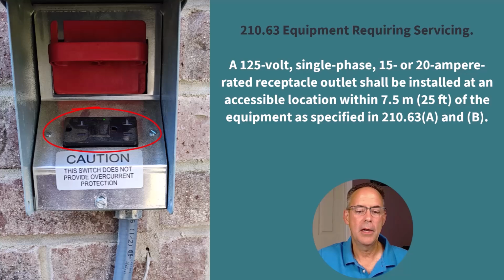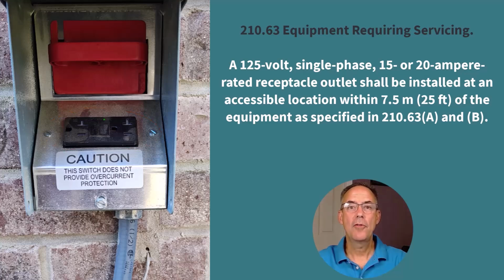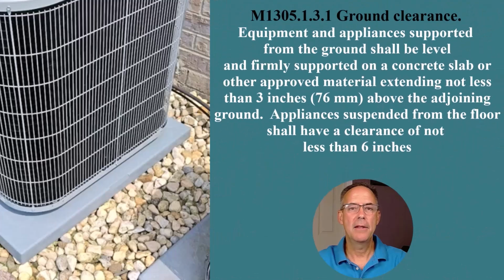In this particular disconnect you see here, it has a GFCI. It's outdoor, so it'd be GFCI rated, and it's part of the disconnect. But within 25 feet of equipment requiring servicing, which AC equipment does require the servicing, you'd have to have a receptacle.